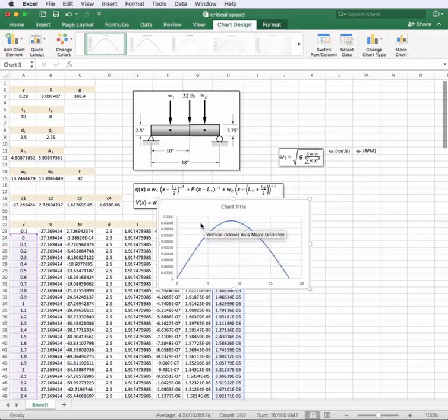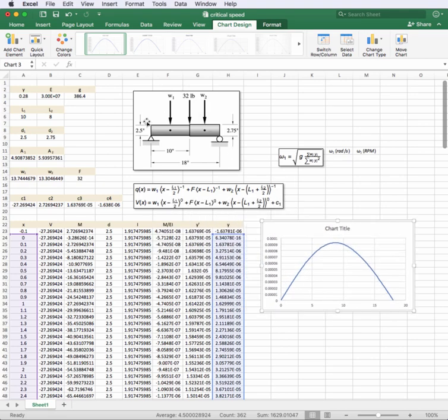And notice we're not deflecting very much. That's like 1/1000th of an inch right there, but again, that's not much weight on such a beefy shaft. And that is, again, just the deflection only due to the gravitational loads, the weight of the shaft itself, and then the gear that's sitting on top of it, like that. But it is the deflection that I need to do my little formula here.